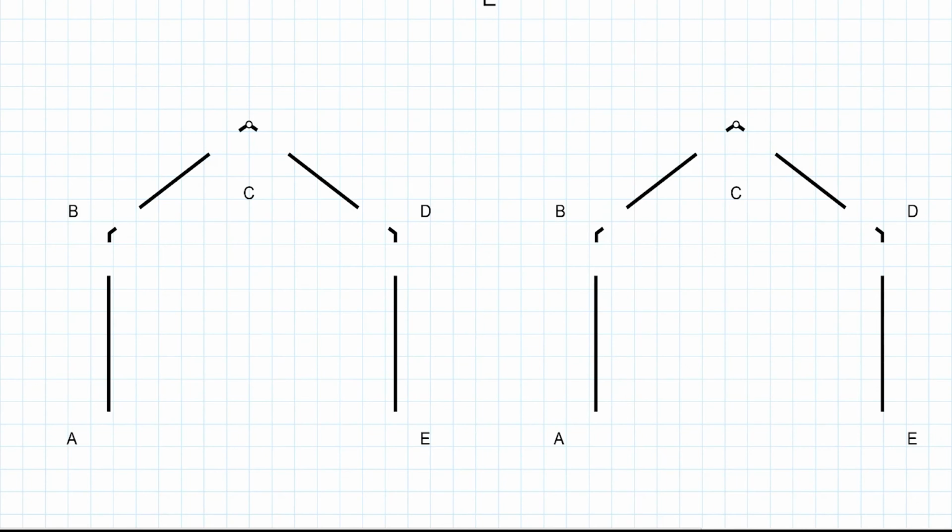Okay, so we need to look at our free body diagrams. I can't fit everything onto the page, which is unfortunate, but obviously you're taking the information that you have in your free body diagram and bringing it down and drawing it onto the shear force and bending moment diagram. The first thing, in this context, is we have to adopt a sign convention. For us, it's as if we're looking from the inside at the bottom of the beam. It doesn't matter whether we're looking to the left or to the right, we're going to be looking at the bottom of the beam.